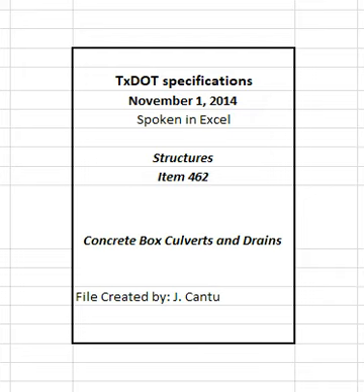Discontinue further production of precast sections when fine cracks on the surface indicate poor curing practices until corrections are made and proper curing is provided. Repair machine-made precast boxes in accordance with DMS 7310, reinforced concrete pipe and machine-made precast concrete box culvert fabrication and plant qualification.